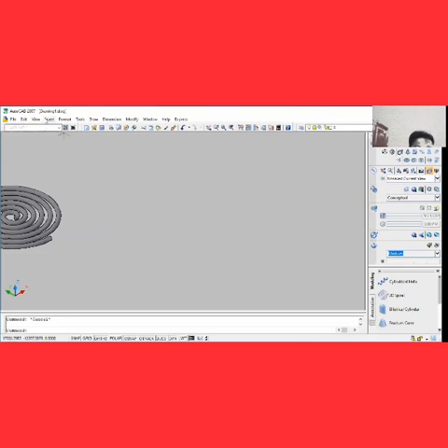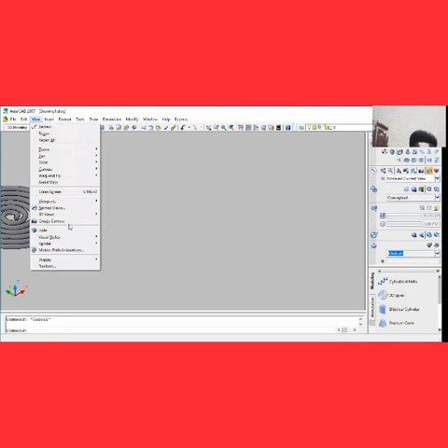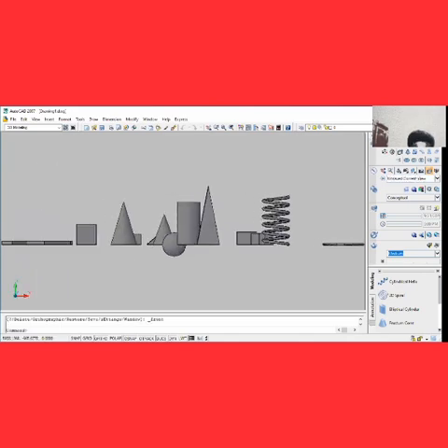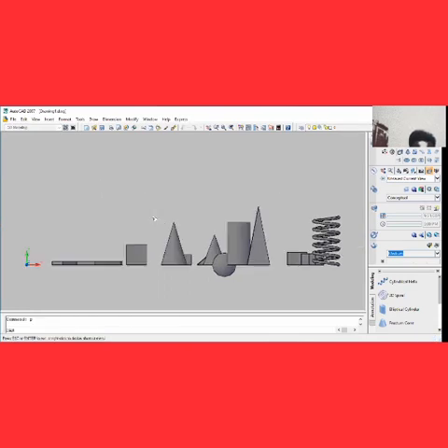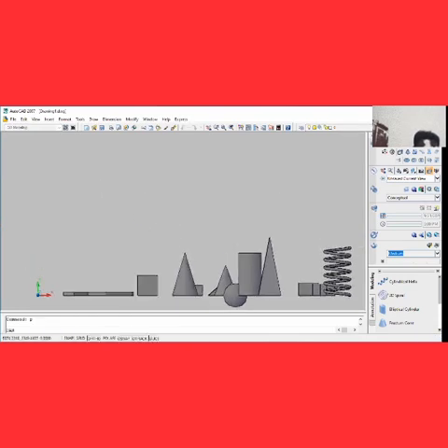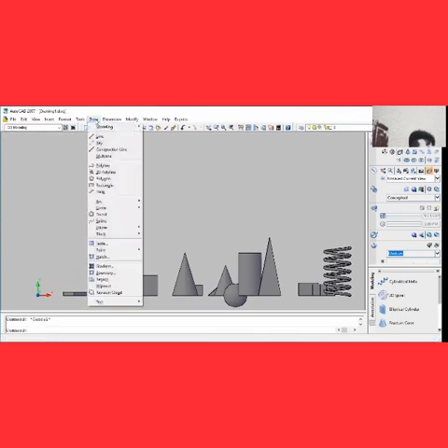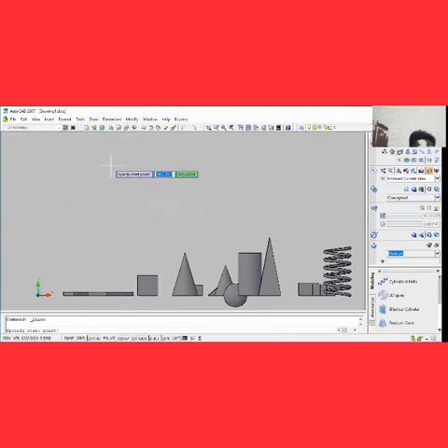Okay, let's go to the front. You have to go to your front view. So you come to the front, you click on front view. After clicking on front view, you press P, enter, so that you get space where you can do it, and then exit. So now, let's take our polyline command, draw polyline.